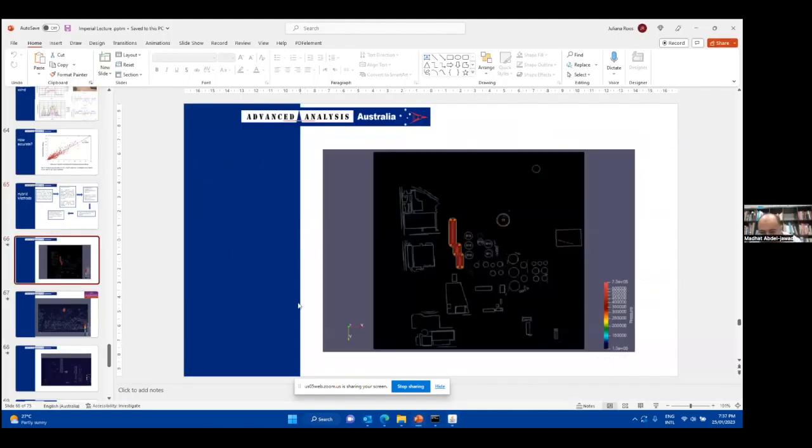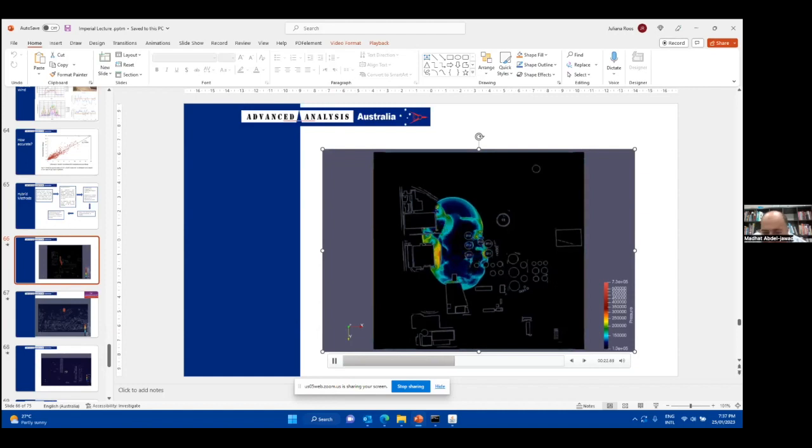Actually, here's the kind of results that you should expect, right? So this is a Buncefield case. If you could see my presentation here now, you could see the explosion propagating outwards. You should be able to see this on your computer if you run this, and the shock wave reflecting off first the North Gate and then now the Fuji building, and of course off the tanks, and you could see pressures in excess of 4 bar.